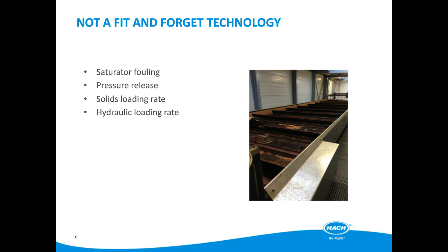The solids loading rate needs to be checked to ensure the DAF is not overloaded, which would result in poor effluent quality and hence load entering the saturator with the risk of reducing efficiency of gas transfer. Also, the bottom of the DAF tank needs to be periodically desludged, the frequency of desludging being totally site dependent. Too frequent desludging results in low solids, but infrequent desludging could mean the solids content is too high to pass through valves or pipework, requiring a complete shutdown.